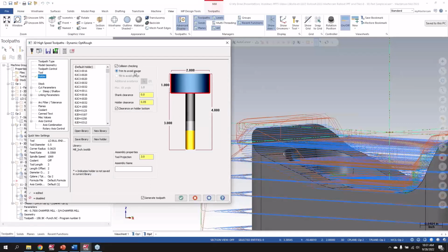So, depending on the part, say you're working on a casting or a part that's on its third op, and there's a little ear of stock hanging off where there isn't necessarily any of your machining or avoidance geometry. It'll still look at the stock model to avoid any collisions with the holder.